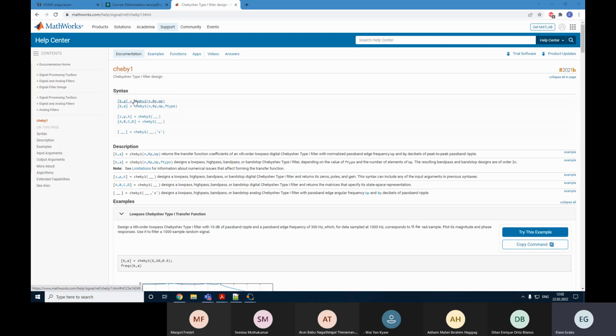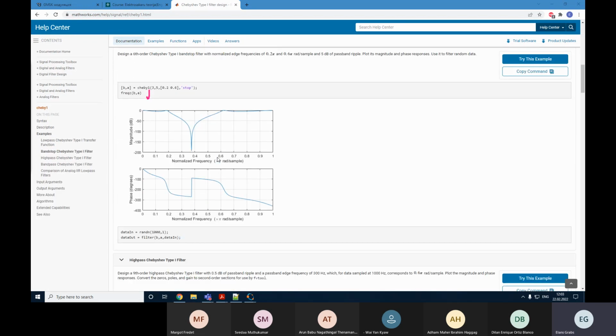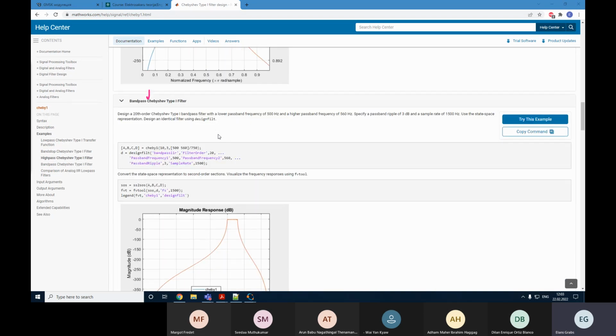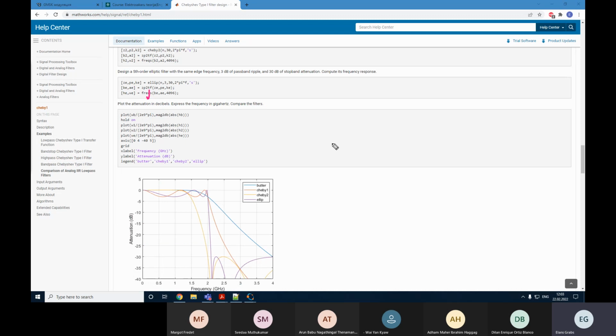So this Chebyshev has multiple parameters. First of them is the number of delay units, right? So in the FIR filter, you had as many delay units as you had number of impulse response samples, right? Here, however, we have loopback, yes, we have feedback, and basically because of that feedback, we don't need that many delay units. So it's quite normal to use like 10, 11, yes, as this number of delay units.